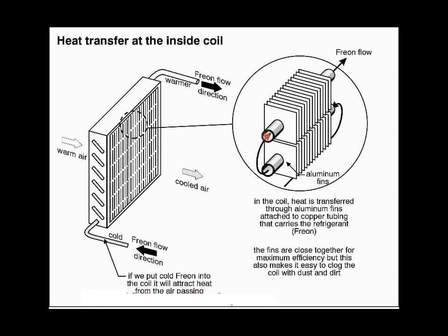I have shown the cooling coil which is like this, and here, these fins are aluminum fins mounted on copper or aluminum tubes, so that these coils get cooled through the increased area provided by the aluminum fins, which is shown here also.